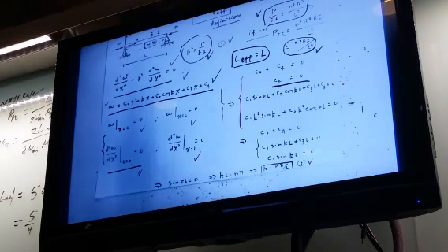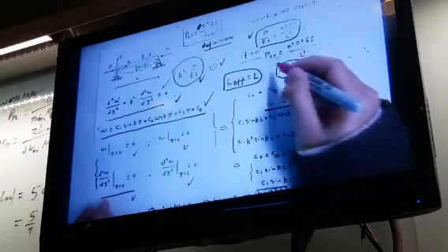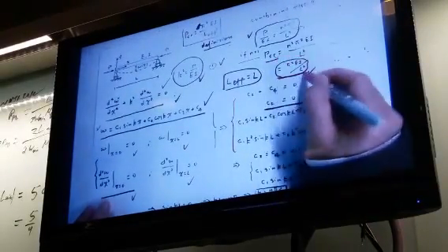So different setups will be here. Different structures will have different boundary conditions. You can form different four equations. You can form four different 4x4 matrices. And to have that determinant 0, you can get different K. This is why when you have different boundary conditions, you have different critical loading profiles. And when you finish the calculation for this structure, you can calculate what is PCR.